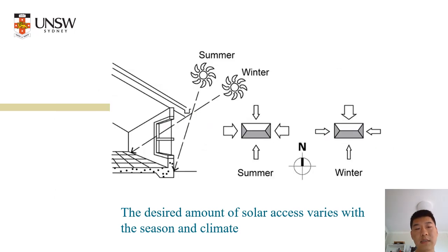In Sydney, the sun is located on the north side, so most living areas should face north to allow rooms to receive a long period of sunlight in the winter. Suitable eaves should also be designed to protect the rooms from direct sunlight in summer. As shown in the figure, the thicker arrows indicate that rooms in this direction receive more sunlight.